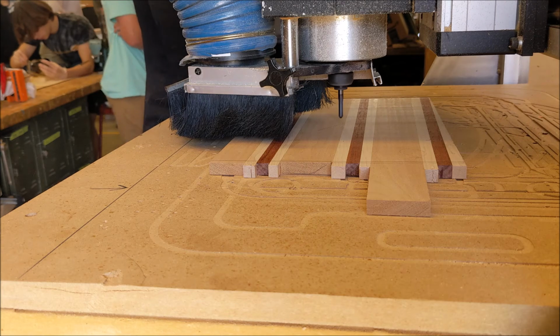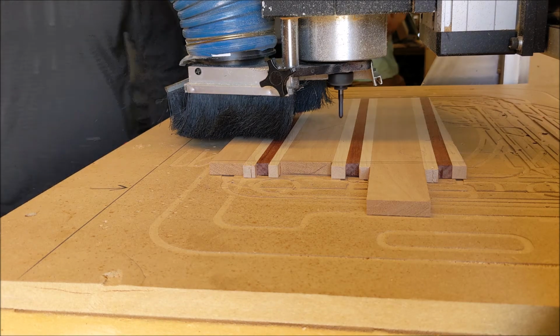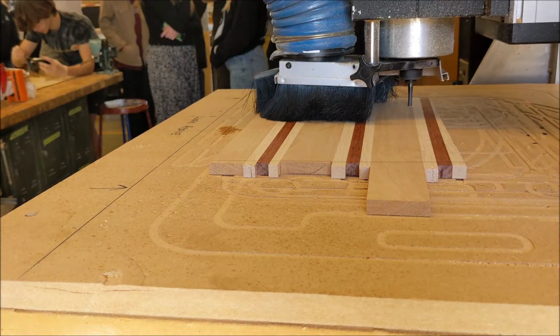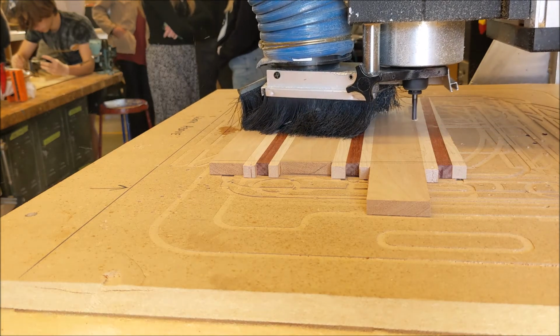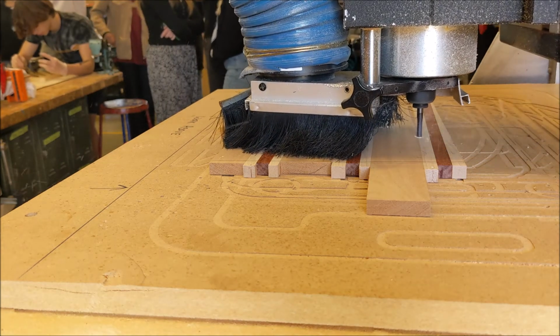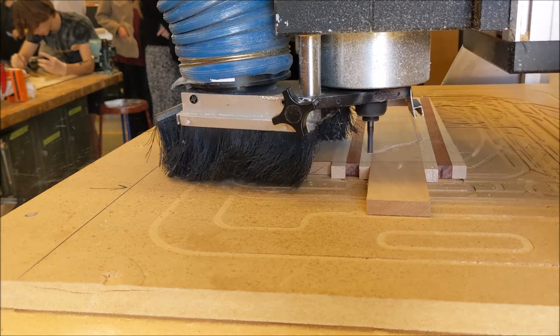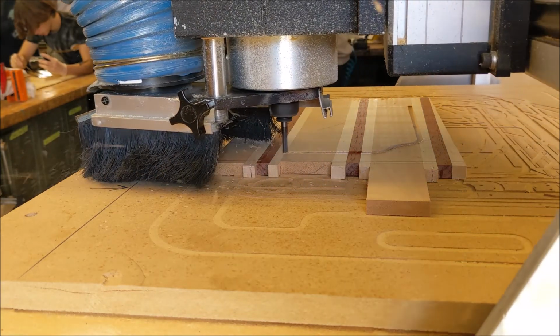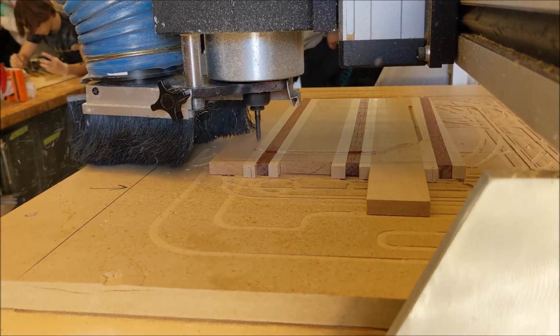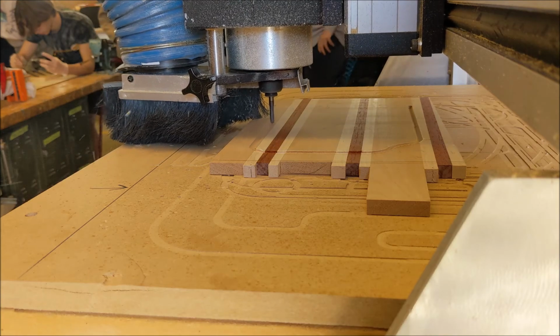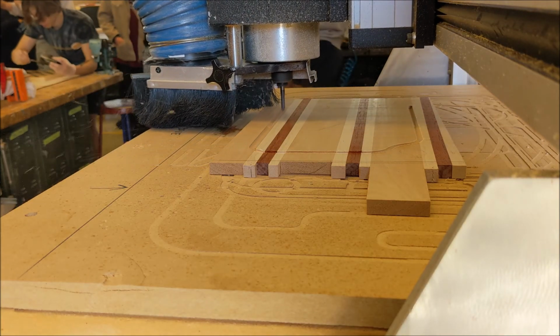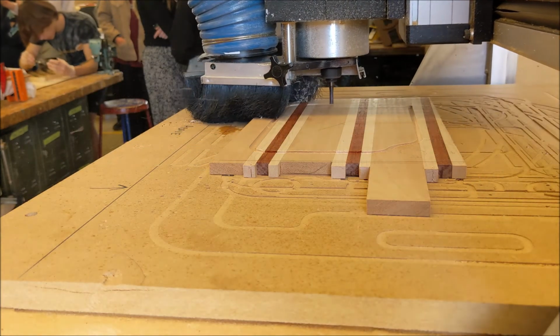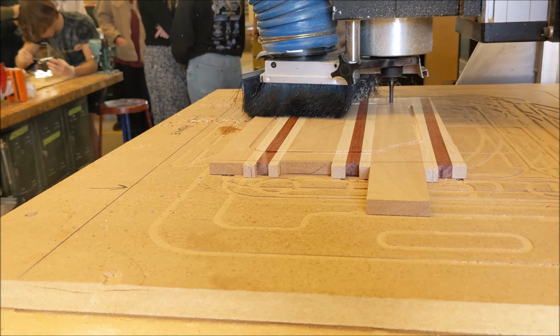I'm going to cut out this one more cutting board and just kind of talk you through it. The router is set on 16,000 RPMs. That's the speed of the rotations. This is a 1/4 inch ball end mill. It is following a contour around. The depth here is only 1/8 of an inch. So my depth of cut is set greater than that. Just going to cut this blood groove out in only one pass.